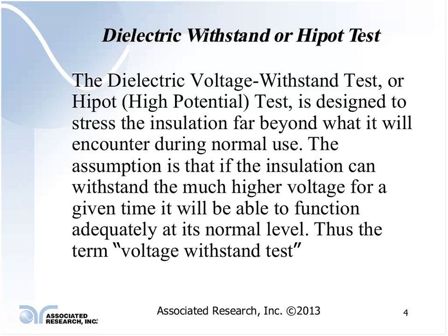It's assumed that if the insulation in the product that you're manufacturing can withstand this much higher test potential for a given period of time, it will adequately function normally throughout the life cycle of the product.